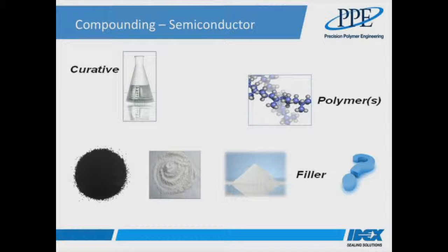The plasma resistance of these types of purely organic products is generally not as good as the inorganic filled materials or the silica-filled materials, but they have the potential advantage that the byproduct of degradation processes can be volatile and therefore doesn't lead to particle generation or particulation of the elastomer. Longevity is therefore traded off against cleanliness, but it's particularly relevant to processes at the forefront or leading edge of technology and for critical process tool locations such as chamber lid O-rings, isolation valve O-rings, slip valve door seals, or any other area that's effectively plasma wetted.